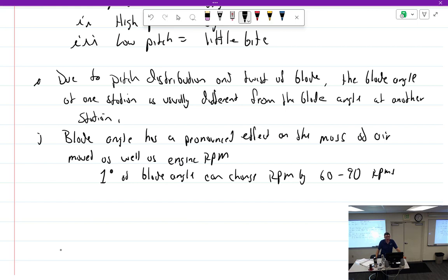Why? And I'm going to show you why, but it's because the blades are stalled. And they're hitting it like a paddle. Wow, because of the incoming air. So it's like the angle of attack is flat against it. You don't realize that, but it really is. You think it's like this, but it's really a bad angle of attack. So you have this paddle out there that's not really an airfoil. You think it's hitting it like this, but it's not. It's hitting it like this. Does it sound bad? No, you don't notice a difference. It's a normal sound that you hear. So we don't think anything of it, but it tells you your engine health.